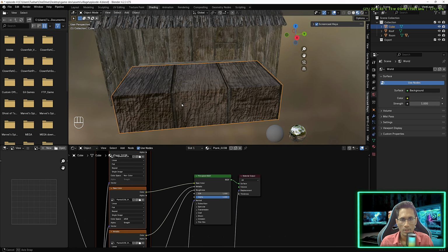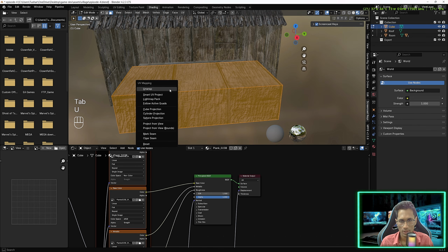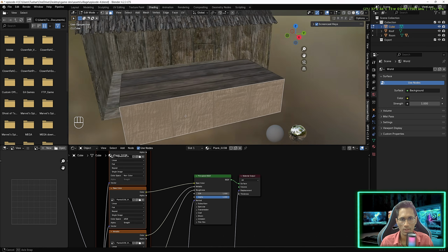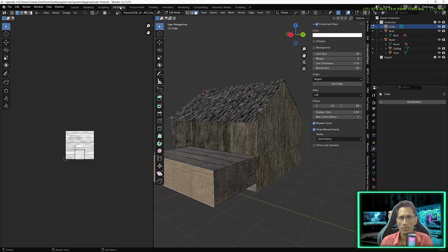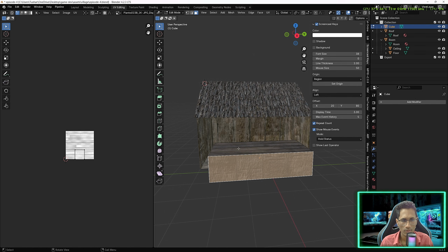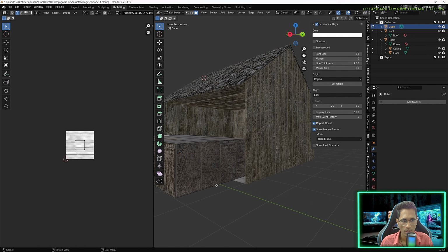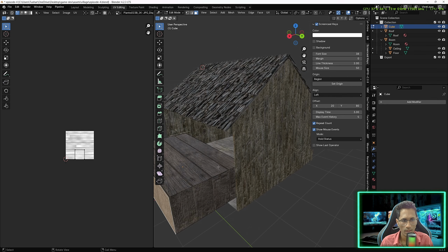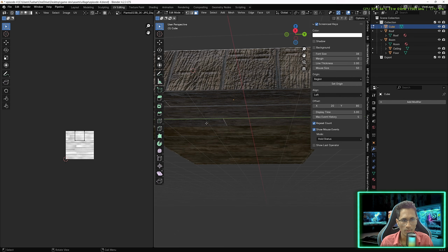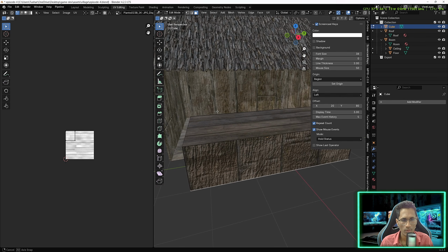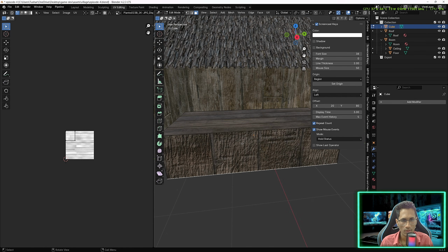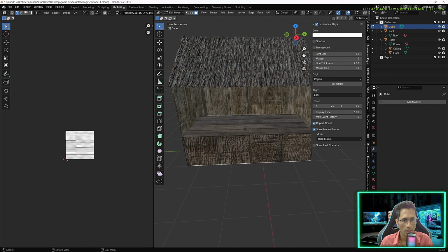Great. Now what we need is, if we go in the edit mode, press U, Smart UV Project 66 degrees, unwrap, and we have our textures properly separated. If we go to UV editing, you will see I have to texture all 6 faces. Okay, so this face is same. This one is similar to the back one, and the top one is similar to this one. So what we can do here is we only do the UV arrangements for 3 textures, and rest of them will get arranged automatically. How do we do this? Is by using the mirror modifier.